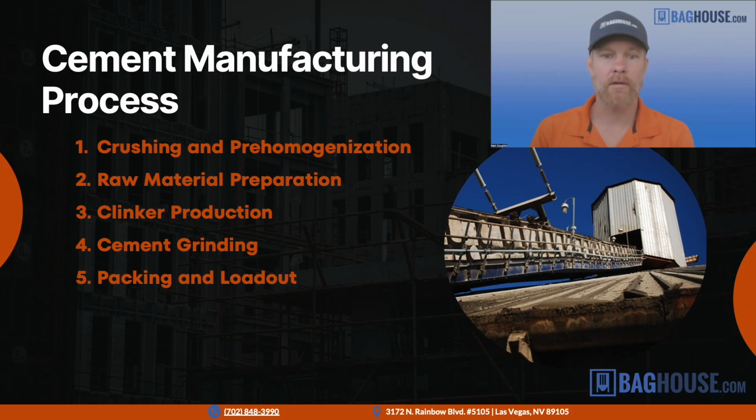After that, you've got your clinker production, where you're going into the preheater and rotary kiln. Materials are heated to very high temperatures. Clinker nodules are formed. You've got hot gases and fine particulate leaving the kiln, which require effective gas cleaning. At this point, we start looking at dealing with temperature and potential chemical challenges. You can't just have a standard dust collector with a 12 gauge sheet metal enclosure because you have really high temps. And what happens to those high temps when they cool down below the dew point? You have moisture forming in the baghouse.